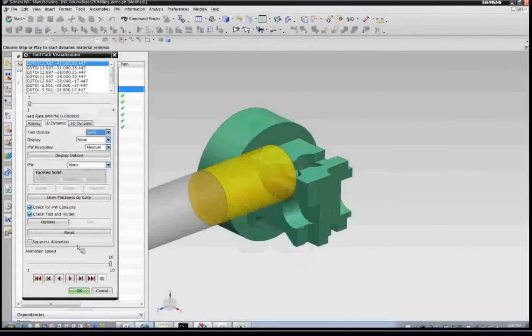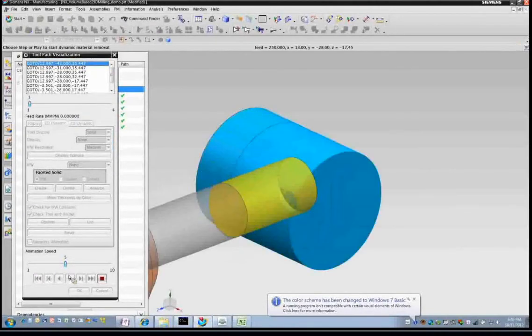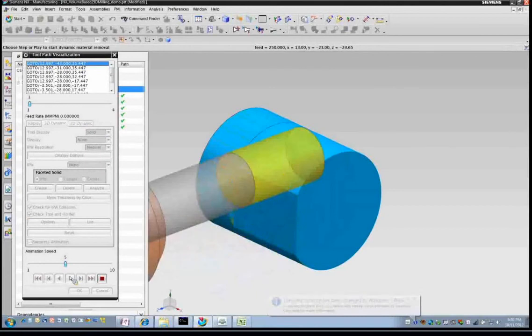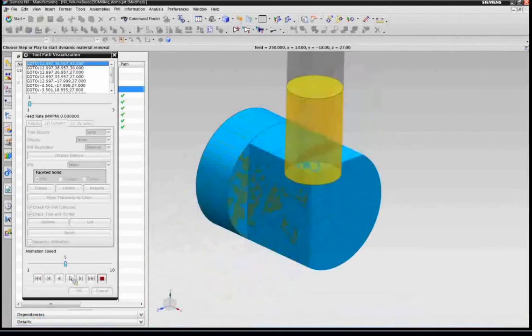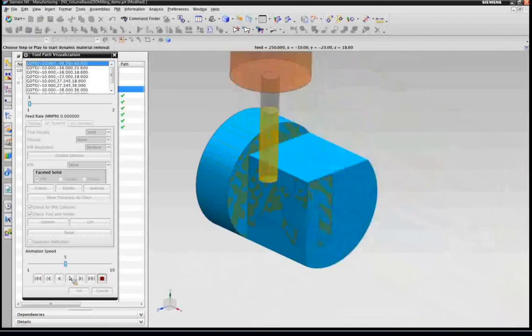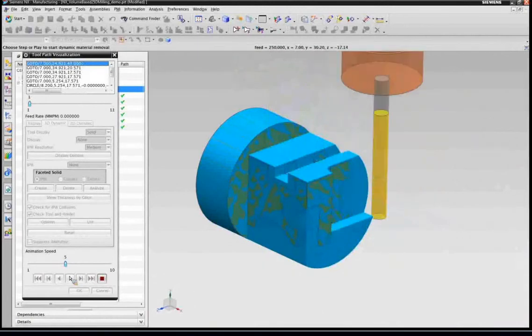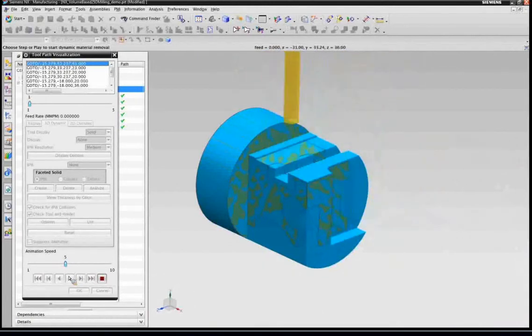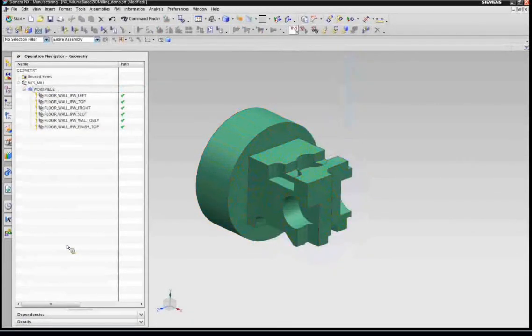I want to show you briefly what we've accomplished with those 5 operations, and you'll see my entire toolpath. Showed you just 2 before. You'll see the very big toolpath that does a single pass, 2 cuts through the slot, the no floor operation that goes a little bit deeper, and the finishing of the top. Now, we can do a lot more complex operations. We can do slanted walls. We can do filleted tools. We can do undercutting.